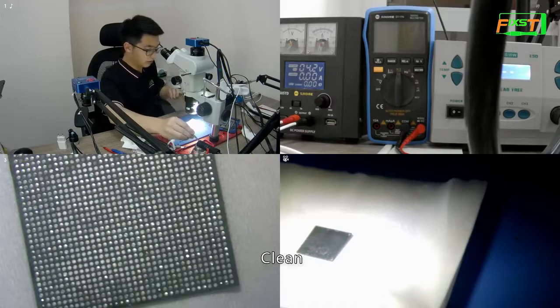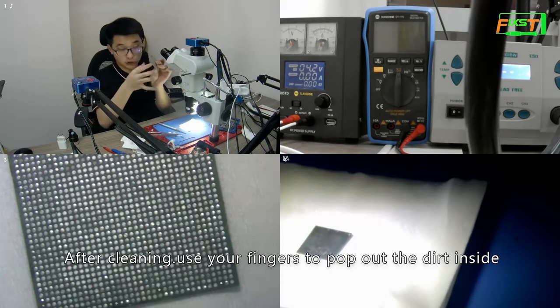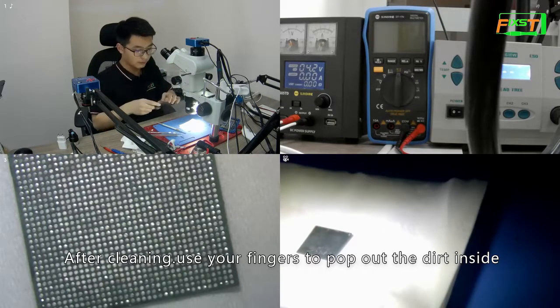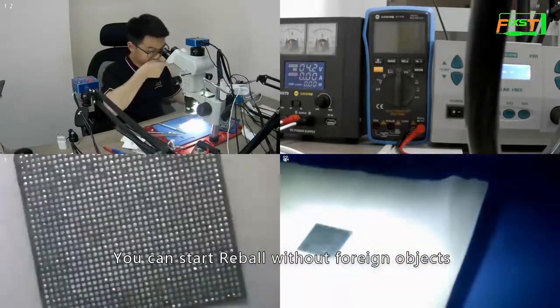Clean. After cleaning, use your fingers to pop out the dirt inside. Then check it under the microscope. You can start reball without foreign objects.